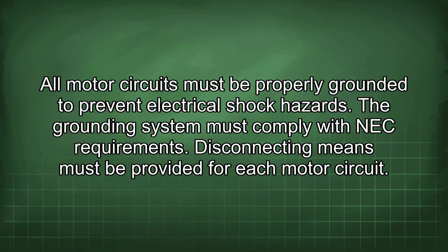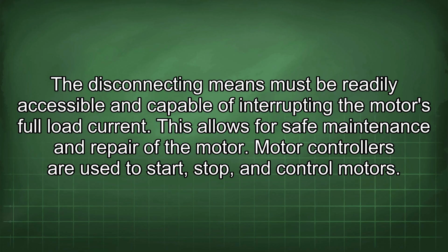Disconnecting means must be provided for each motor circuit. The disconnecting means must be readily accessible and capable of interrupting the motor's full load current. This allows for safe maintenance and repair of the motor.